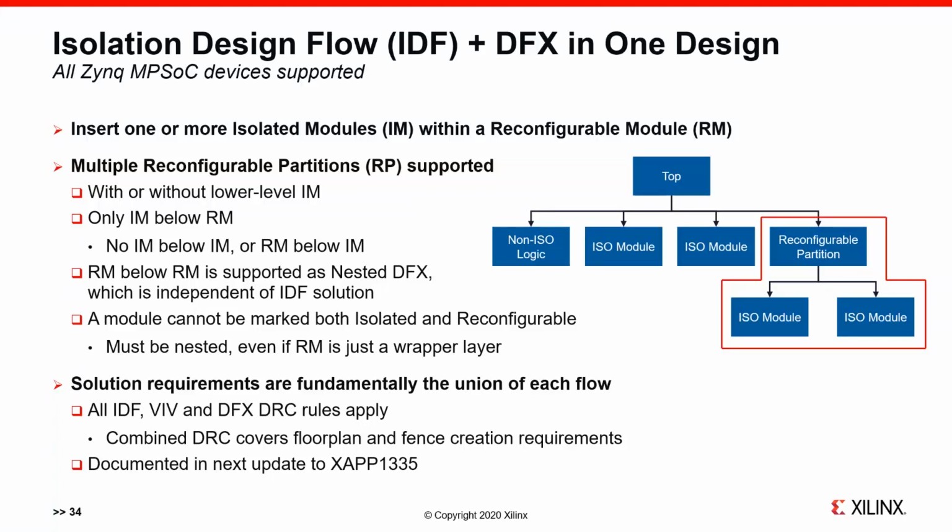Isolation design flow with DFX in one design is going to production for Zynq MPSoC devices. This allows us to insert one or more isolated modules within a reconfigurable module.